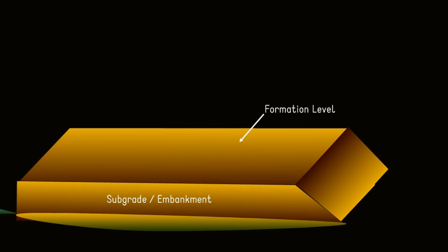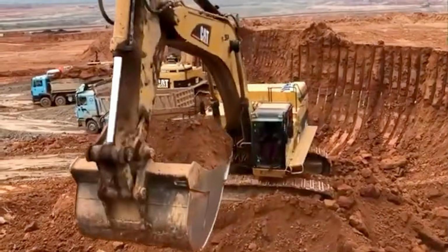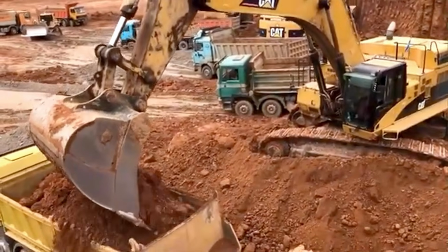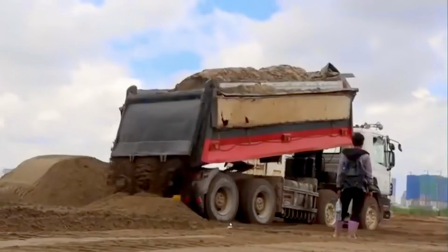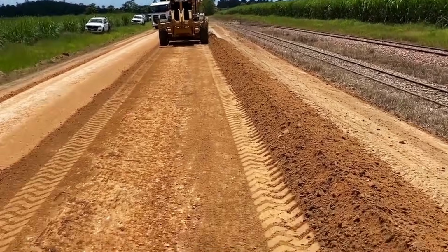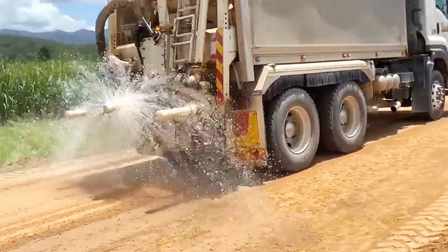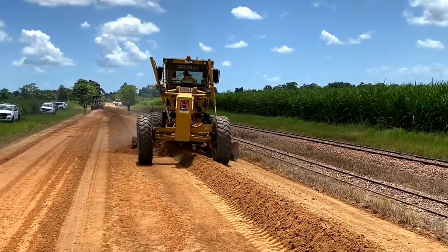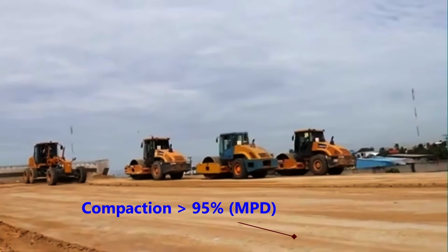If the ground is structurally weak, likely to be subjected to exceptional loads, or is significantly below the required formation level, specified subgrades consist of layers of earth fill, obtained from selected borrow pits. The scope of work includes excavation, loading, transportation, laying, leveling, watering with potable water to achieve optimum moisture content, and thorough mixing before compaction. Compaction shall be carried out to achieve at least 95% of relative density.